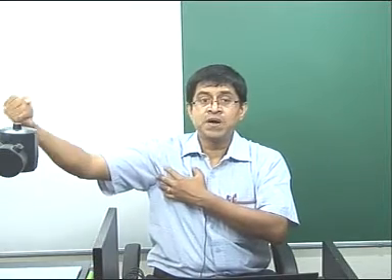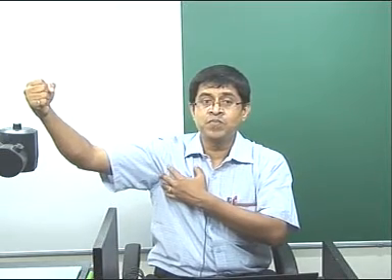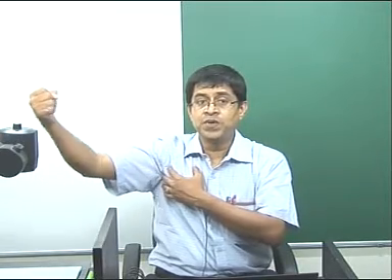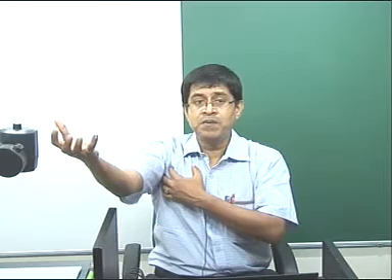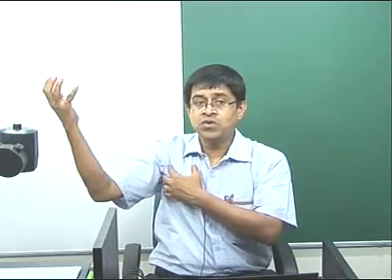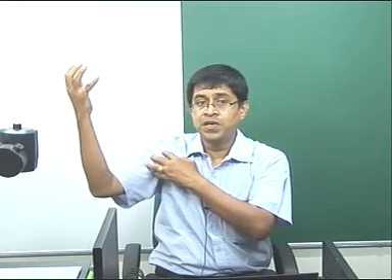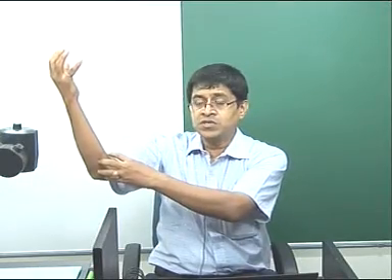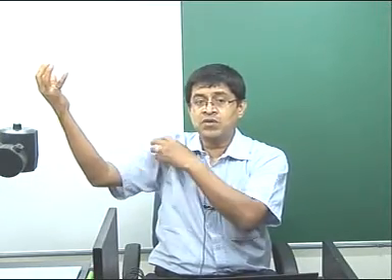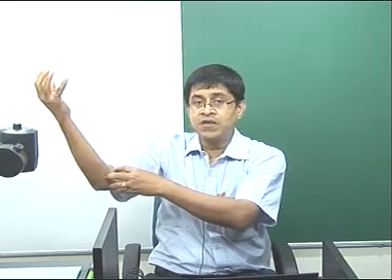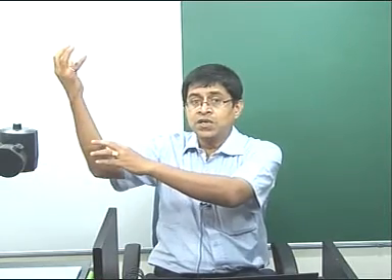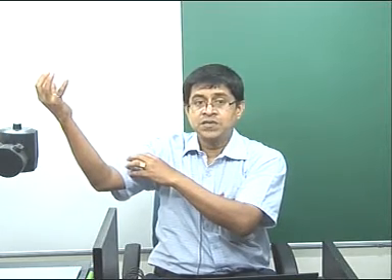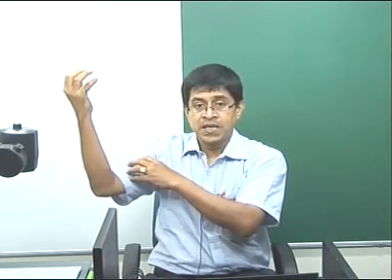So, this is my robot. I want to move from point A to point B. To move from A to B, having some weight maybe in my hand, how much torque should I apply? I am moving this joint and this joint. I can calculate how much muscle torque to apply if I know the motion as well as the properties of these links. That is for control purposes, that is number 1.